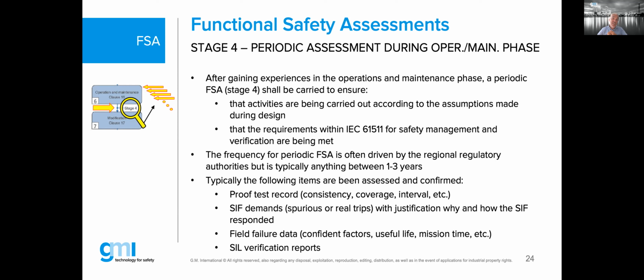And I even know one end user, when you are expiring that time and you were not, by production requirements or by management requirements, allowed to do the test. Well, actually, the safety teams will say you will have to go to shutdown, because they will say your safety performance of your loop cannot be proven. Therefore, they will not take any credit for the potential risk reduction, which is maybe or maybe no longer there.